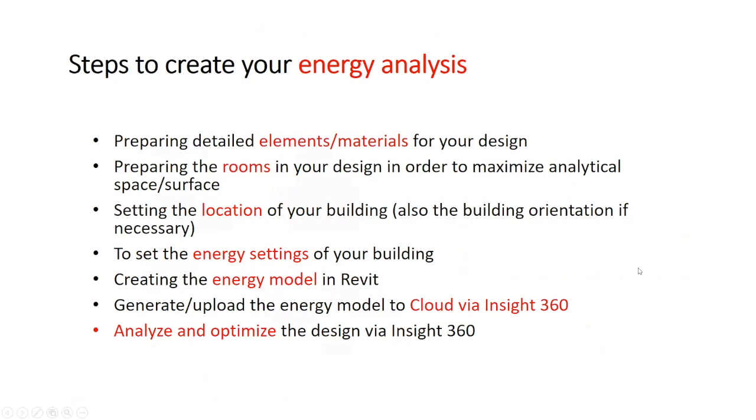So these are basically the steps in creating your energy analysis. Firstly, you are required to prepare all your building elements. As you know, in Revit, you have building elements which consist of walls, floors, roof, windows, doors, and so on. You will need to assign certain materials to these building elements because the materials in Revit have analytical properties in them. These analytical properties will be very important in conducting energy analysis.